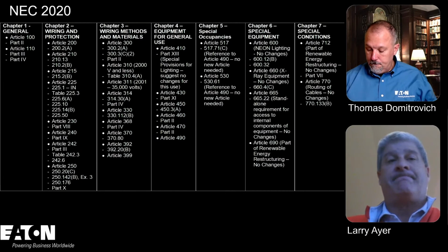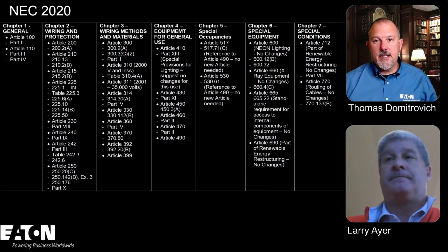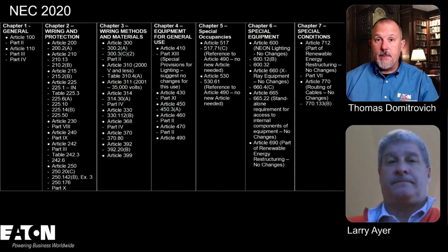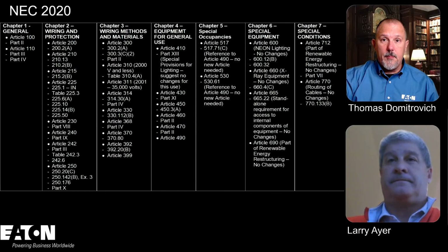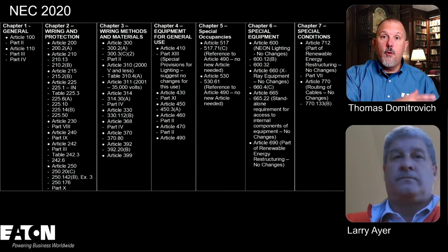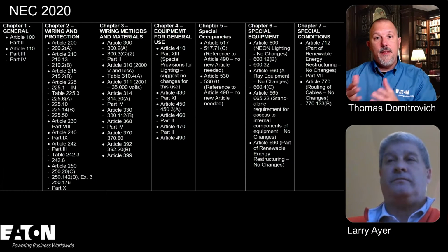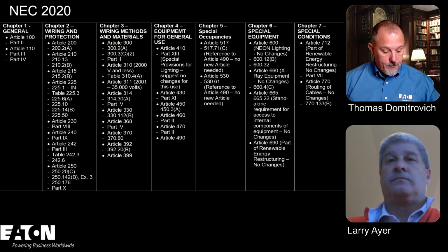Yeah, because the thought process is that 1 through 4 applies generally. So a lot of people think that because it's in one section, it automatically applies to medium voltage, especially if the medium voltage world is silent on it in the code, which I think is another problem. When there's silence on certain topics that we're typically used to dealing with, we apply the rules for 600 volts and less in those medium voltage applications, to your point.